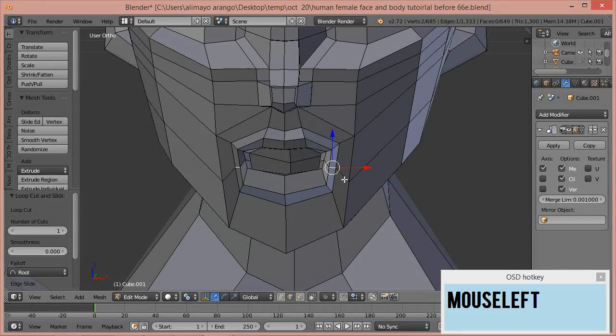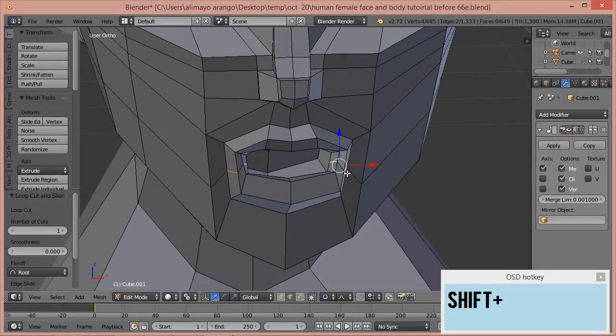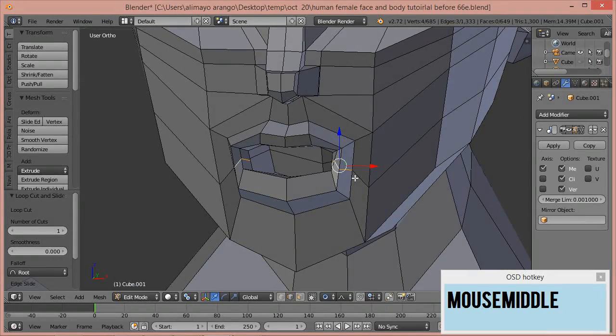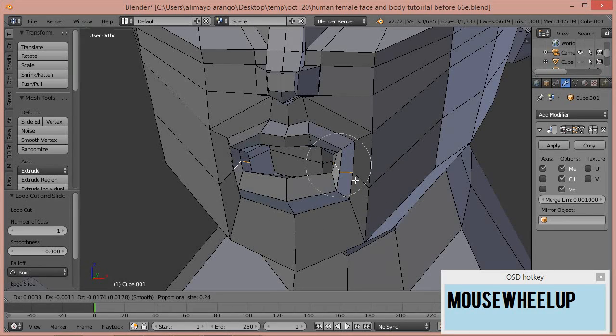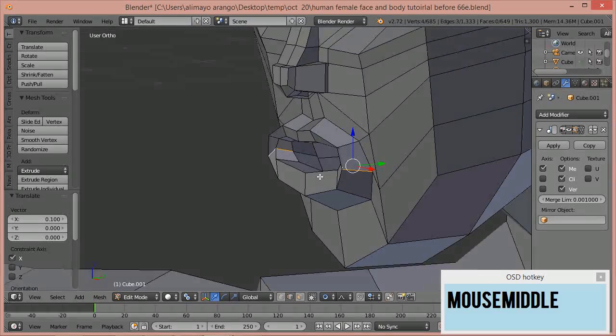And what I'm going to do right here, I'm actually going to press Alt O to turn on our connected proportional edit. I'm going to select right here and here. I'm going to hit G so I can see the area of influence. I'm going to roll that down. Now I'm going to hit X to take that out some to the side.